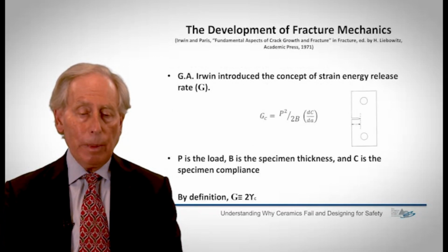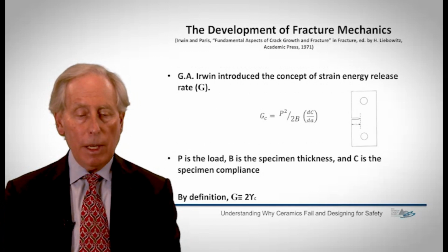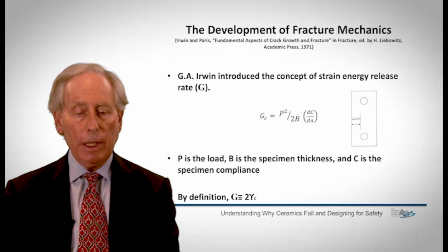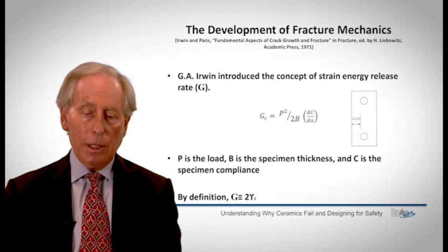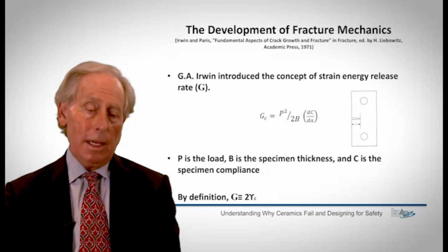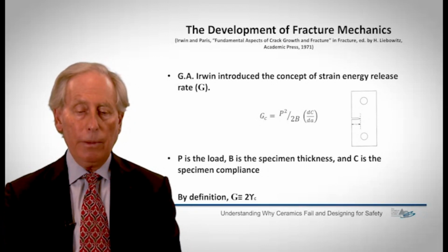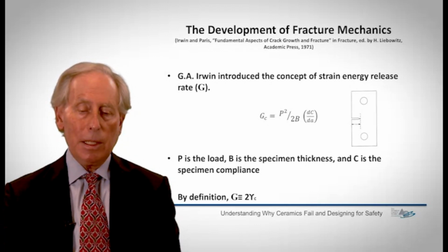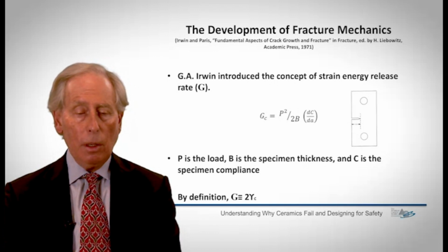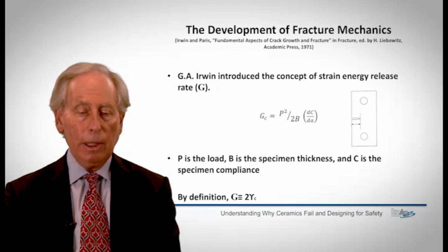With the development of fracture mechanics, and I mentioned George Irwin's name earlier, he introduced the concept called strain energy release rate. You see a little specimen that I show right here. In his case, he looked at metals. I mentioned earlier the failure of brittle metals as well. If one pulls on this specimen, there is a small notch introduced, and that notch and a small crack at the end of it will grow with time. And the term that he coined was strain energy release rate.